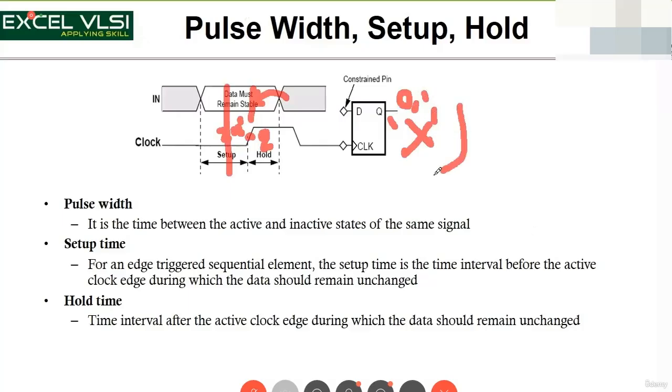That is what will be given in the dynamic simulation, whatever I showed you. If you are doing a timing simulation and the numbers are not met, then instead of the definite values 0 and 1 that you saw in green color, you will see X in red color, which is an unknown. X means there is nothing called X. It is just a state to represent that it may be 0 or it may be 1. That is in simulation. So these are three important criteria.